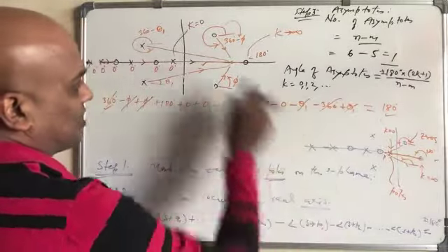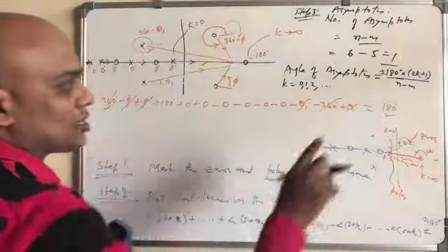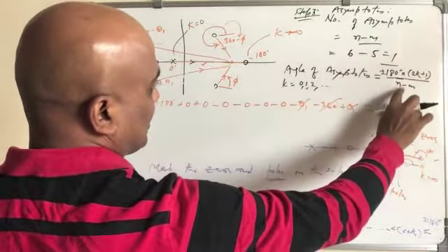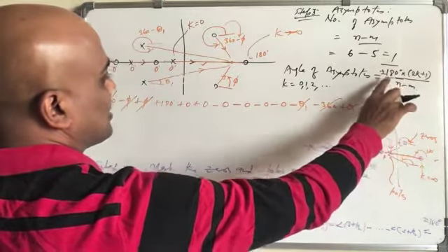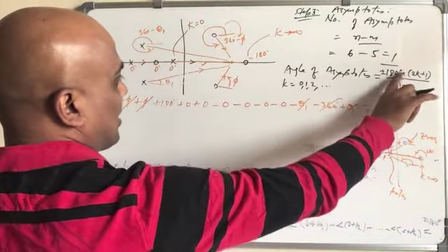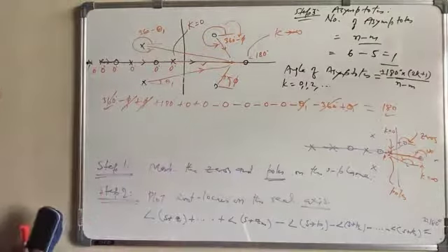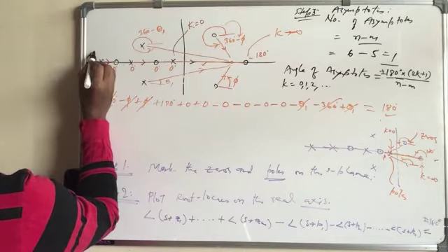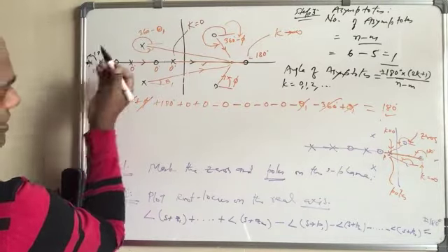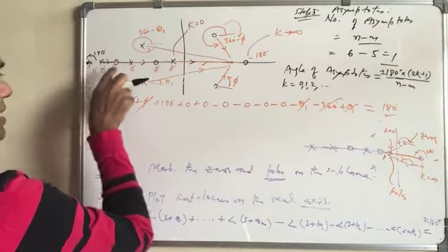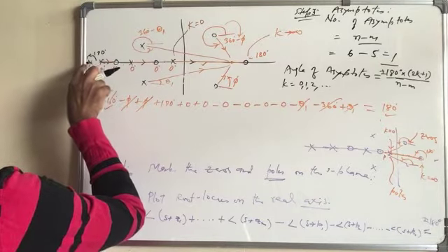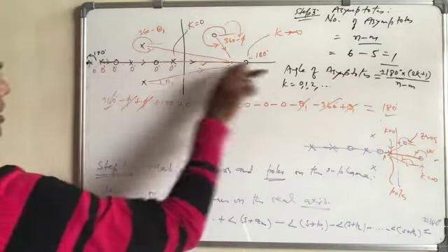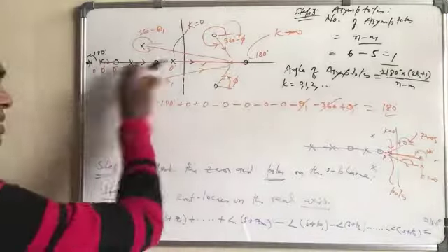So we can see through an example what I mean. When you have the number of asymptotes equal to 1, what do you get? You get 180 degrees only, plus minus 180 degrees, meaning that the angle is 180 degrees or minus 180 degrees, the same thing. So the asymptote is aligned 180 degrees to the positive x direction, right?